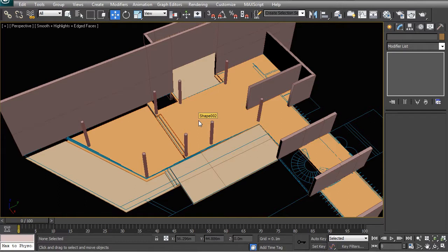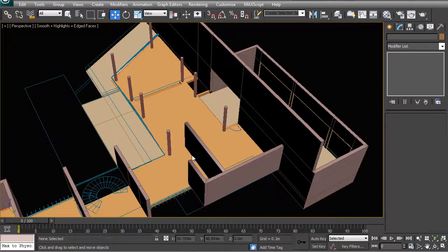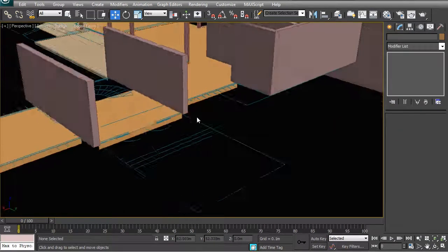It's very difficult to try and backtrack and try and add an instance modifier, for example, or an instance function, or any such function to your objects once they are created. Once it's done and they're not instance, it's too late. So just think about it ahead of time, how you want to have things made, how you want them to be editable, and how you want to use them towards the end of your project.